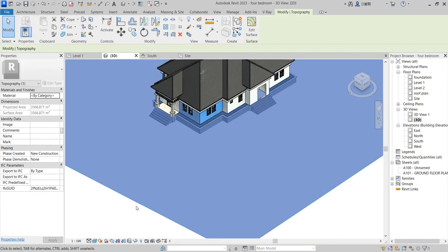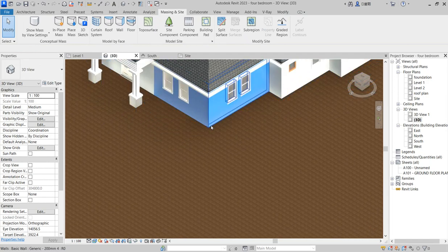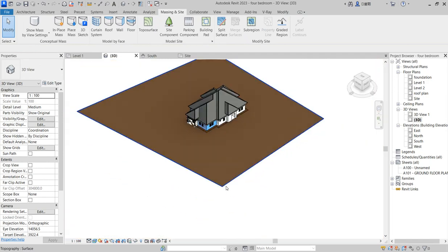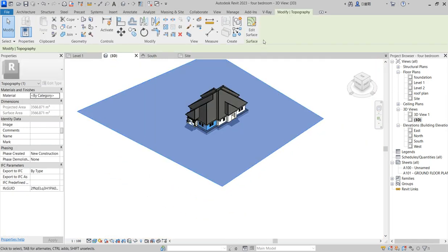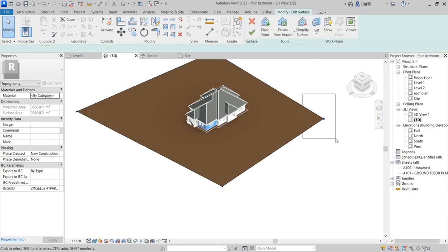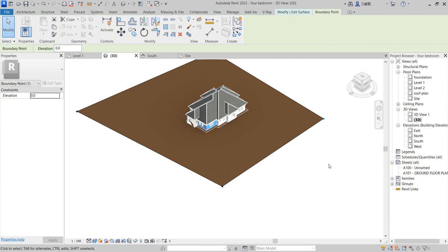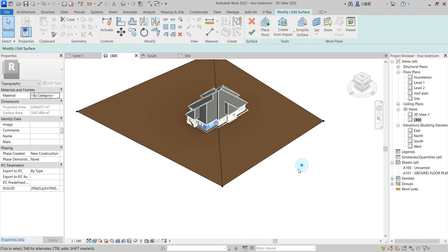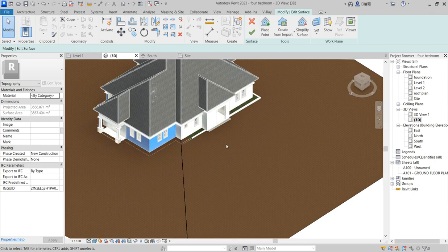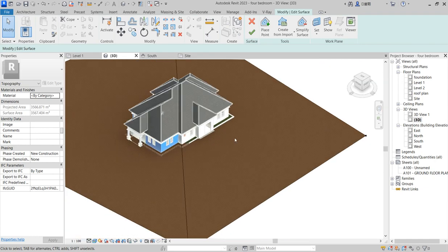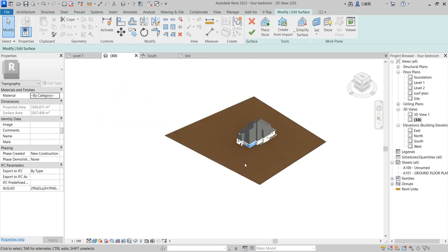What you see when you click on it, it's already cut off most of this space that's there. So how do you edit that? That's why we click here and you begin to select individual sides. When you select this one, it's going to take you to the elevation point. What you need to do is click on the elevation and say minus 1000. When you put it here, you see this side has gone down and this white side still remains at the very peak.